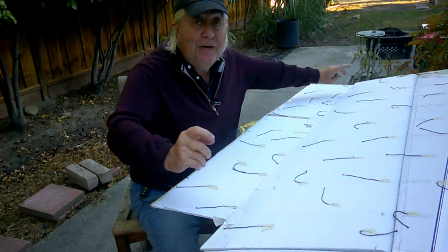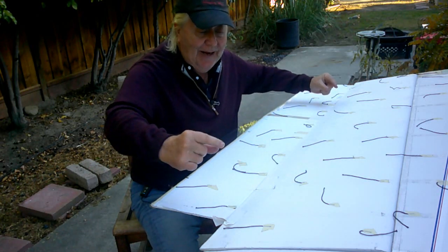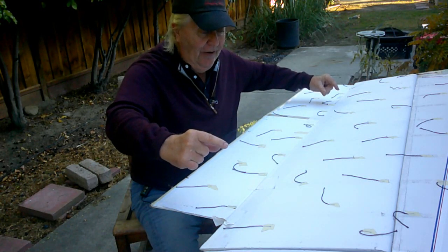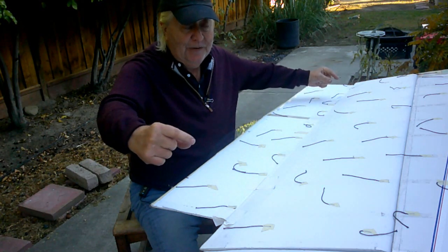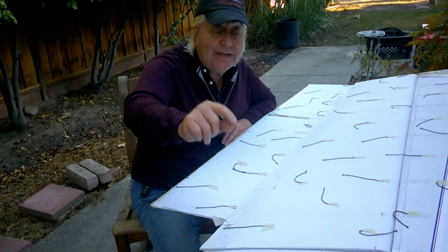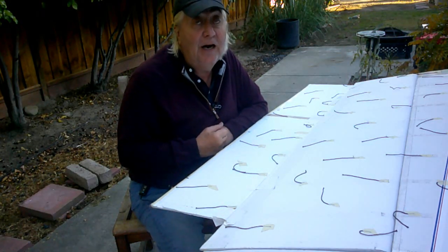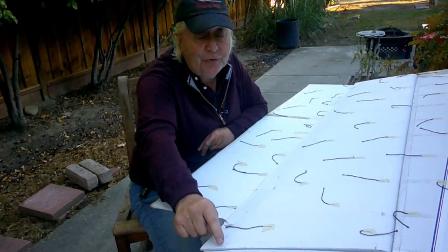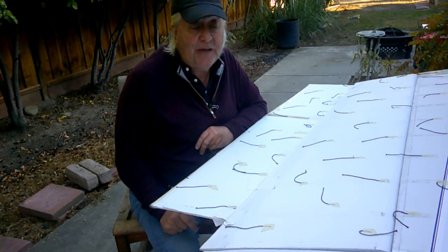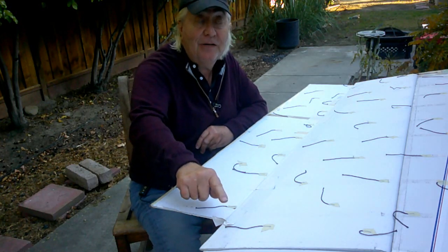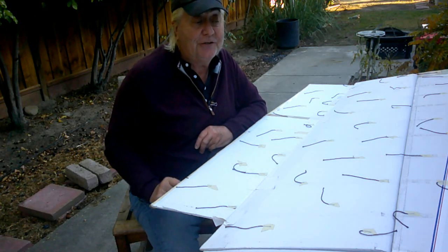And as you finagle the numbers and get the aspect ratio higher, as you stretch the span out and hold that area at 150 square feet, the tip gets really small. That's how you get down to 24 inches. But it looks like the right way to do it is to say, I've got to have a tip chord of 32 inches minimum, because at that stall speed, I want to have 500,000 Reynolds number out here at the tip so that my flow stays attached.